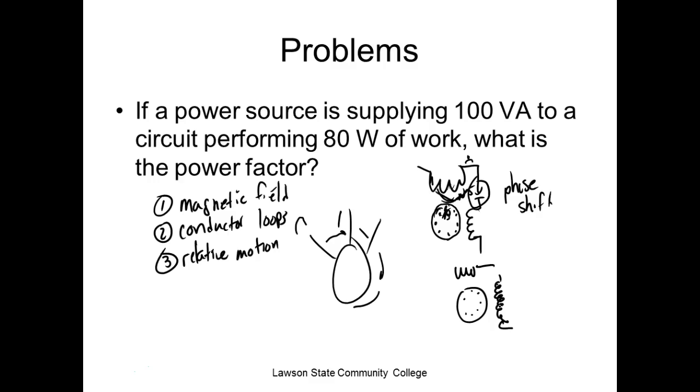Well, we use what we call induction motors. The advantage of induction motors is there's no connection between the rotor and the stationary part, because the current is induced into the rotor by this mutual induction that we talked about. So it works kind of like a transformer does. But the problem is, to get that motor to turn, the field on the outside has got to shift. Well, with single phase motors, it wouldn't shift unless we put something in there that gives us a what? Phase shift. We can either use inductors, those are split phase motors, or we can use capacitors. We call those capacitive motors.